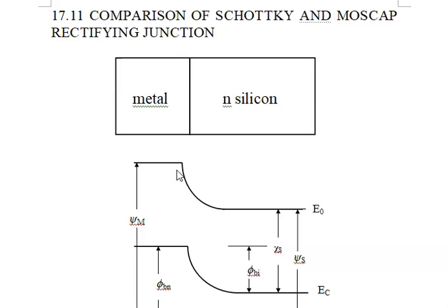And the reason is that inside the metal, in here, we have no electric field. It's field-free region. The voltage is constant, and if there's any charge, it is right at the metallurgical junction, and that is a surface charge. So generally we have sharp corners, and that is something that we try to avoid, but it's there. Whenever we have a metal, we're going to probably have sharp corners. So this is the metallurgical junction. This is where the field is the highest.